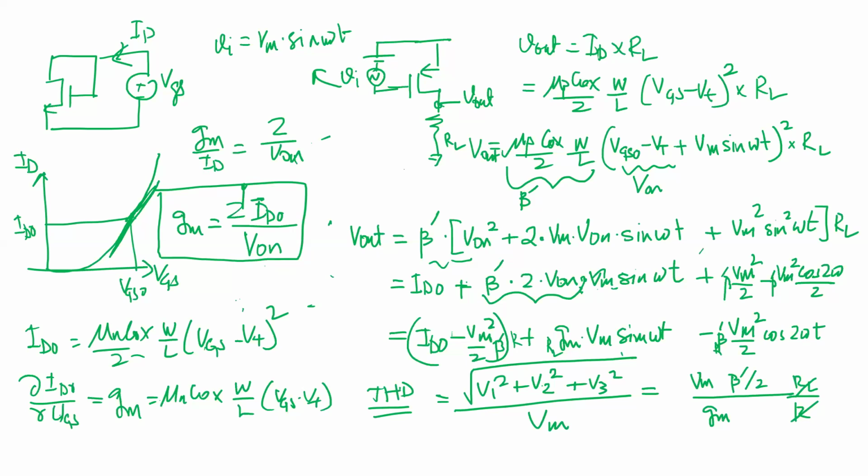See, current source is what? What is the ideal transfer function of a current source? That you put whatever voltage across it, it'll draw that current, right? Which means I can bias this to any point I want. If this was a current source, then the bias current will remain. And the small signal, that is for very small signals, if the output is varying a lot, that gives me the AC impedance. Okay, so that's the reason we use the current sources. Got it? Clear? Any questions?